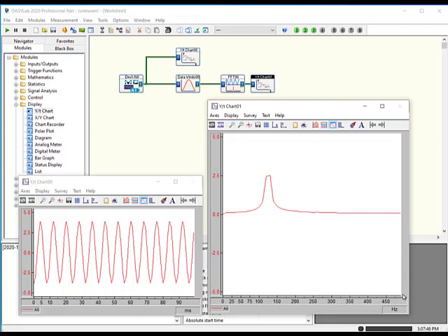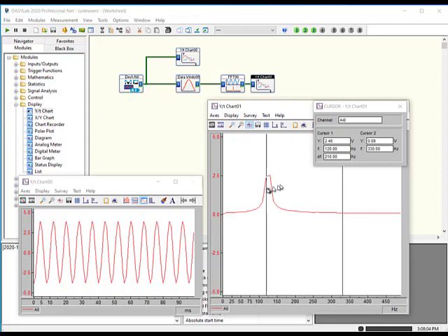The resolution is based on your block size sample rate ratio. So the resolution, we've got 100 samples in a sample rate of 1,000, so the resolution is 10 hertz. And the cursor showed you that. So this is a cursor point, and as I'm moving the cursor, it is moving by point. And I can use my arrow keys to move back one, forward one, and now back. They're overlapped, they're the same value. So that you can see on the cursor that the delta frequency is 10.